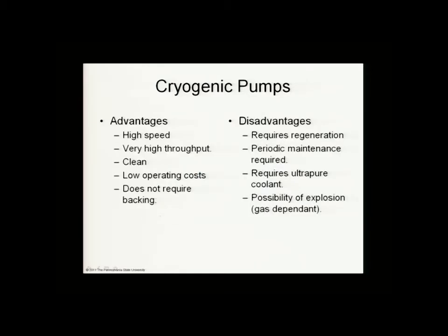So cryogenic pumps have a lot of advantages. They're high speed, high throughput, clean. Well, they're clean. There's no oil, nothing that backstreams. Remember, the liquid helium is there, but it's inside the vanes. Low operating costs, don't require backing. Remember, they don't have that pump to back them. You don't have that constant need.